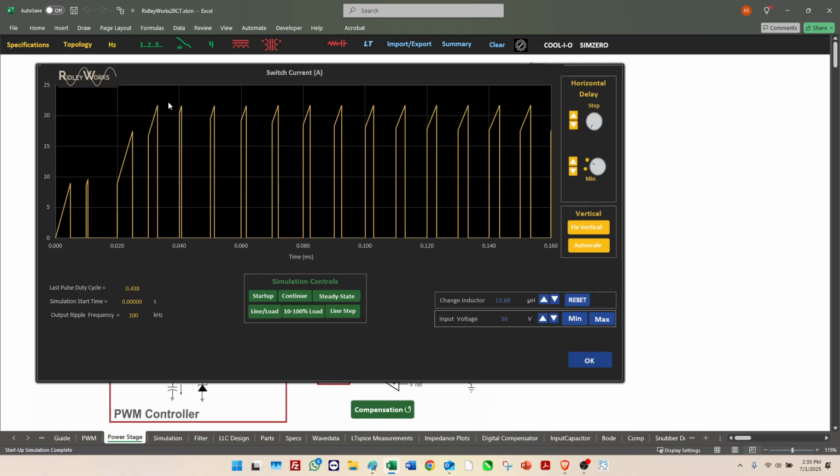And now in this region here, the converter is actually current limiting. Why is it important to simulate current limiting? Well, if you're designing things like magnetics and inductors, that's where you've got to design the magnetics. It must not fail during startup. So you could check your converter during startup, and you've got to see the current limit. Make sure you've got that set properly to operate without saturating the magnetics.